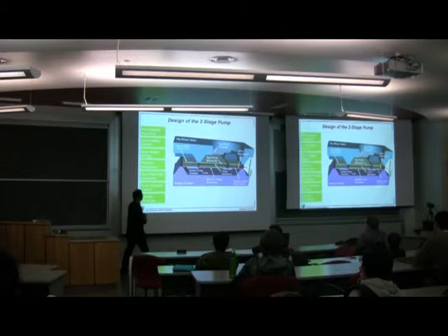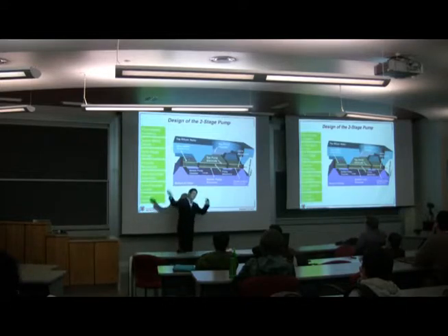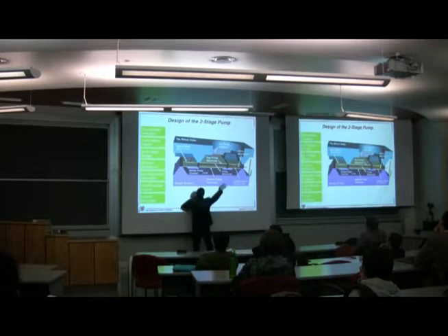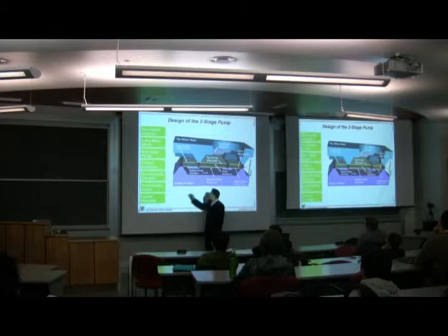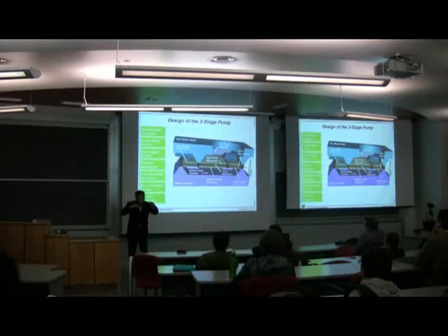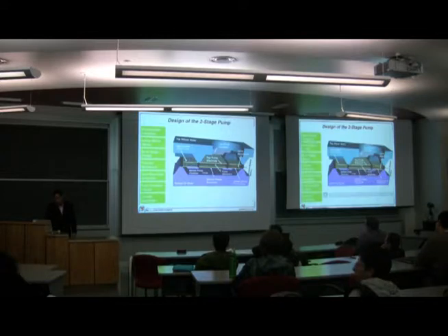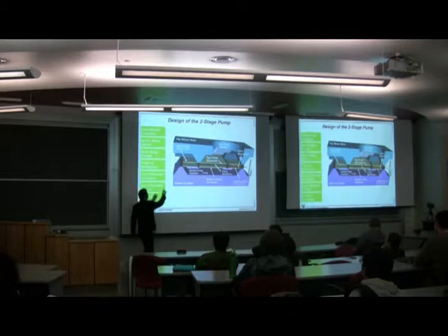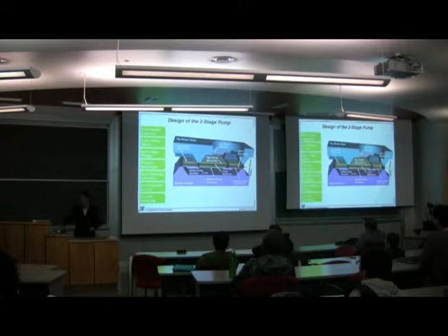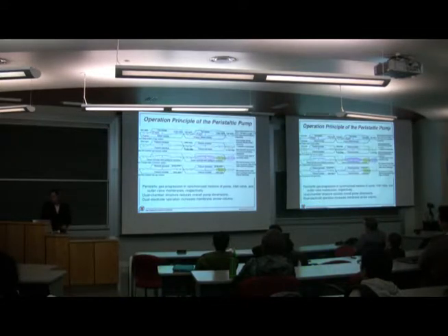This micro device is the same as the previous one. The previous one has only one of these, right? But now we have one, then on top there are two, and there is another membrane which is called the micro valve. It controls the flow. Sometimes you block it, and sometimes you open it. So we made it so that these little gas molecules will pump through this, but because they are connected in series, the pressure will accumulate very high.